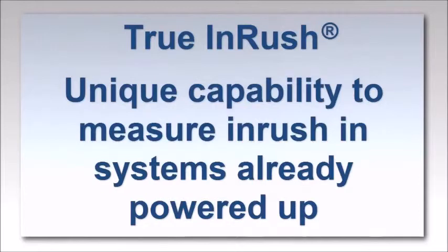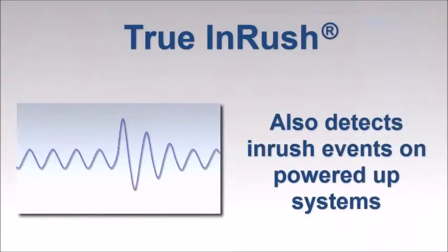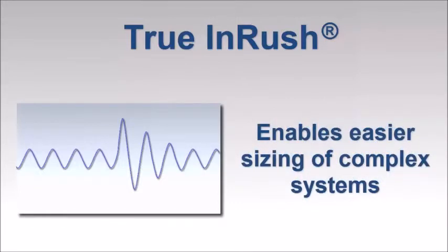AEMC's True Inrush function adds the ability to measure power-up events from devices added to a network that is already powered on. In addition to the initial power-up event, True Inrush can also detect subsequent power-up inrush events that meet user-defined threshold criteria. True Inrush captures all overcurrents, making it simpler and easier to size complex installations correctly.